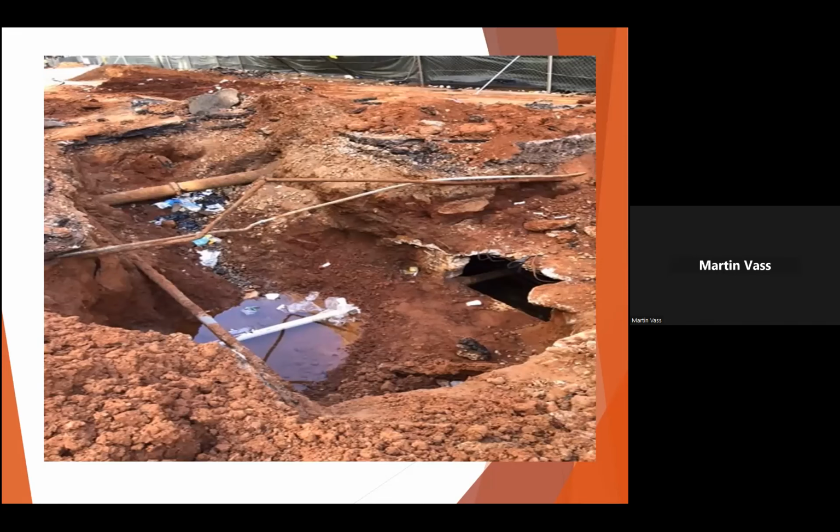And what happened over some period, and we're not sure, this culvert was put in in 1937, a long time ago. And at some time during its lifetime, they broke through from the culvert to a sewer line underneath. I think the idea was any buildup of water in that culvert would drain off into the sewer line. But the problem with sewer lines is they have methane. And over time, methane percolates up and fills this culvert.